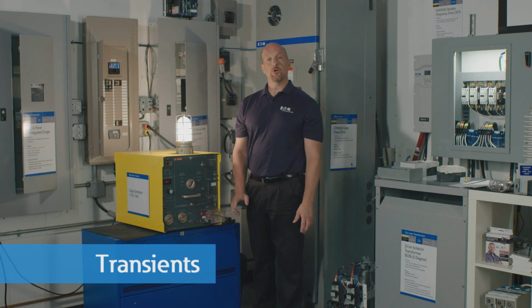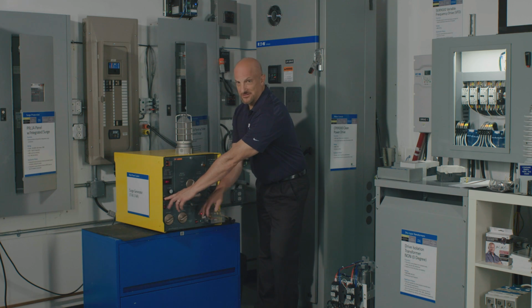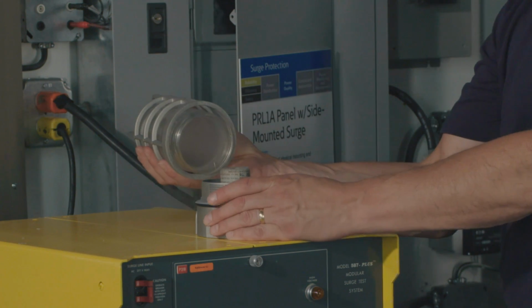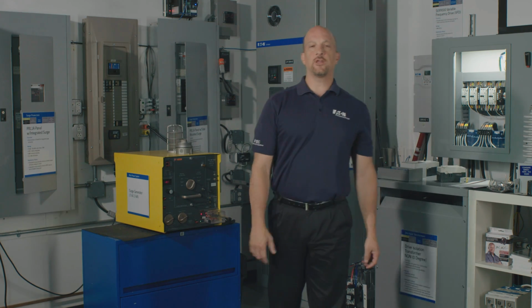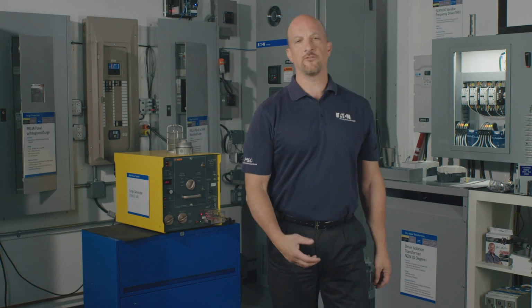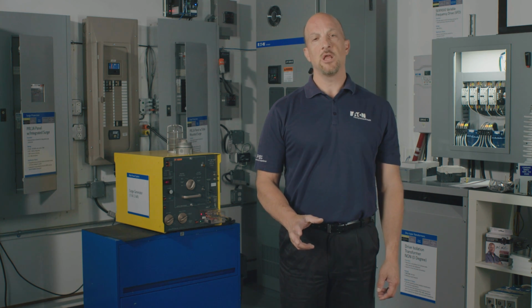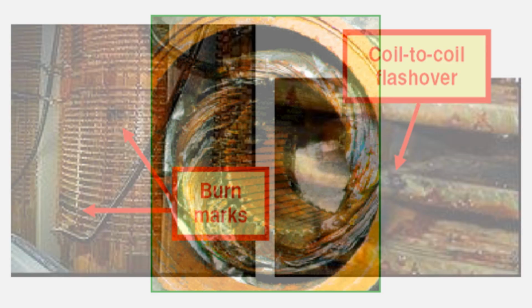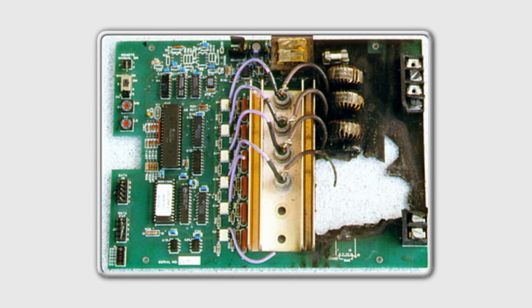Transients or surges are short duration, high voltage events, subcycle events, and their effects can be significant and damaging. Instead of the insulation of a transformer or motor looking like it was baked from harmonics, it will typically have a simple pinhole in the insulation, usually near the end turn. Transients usually result in damage that's hard to recover from. Often the equipment must be replaced.